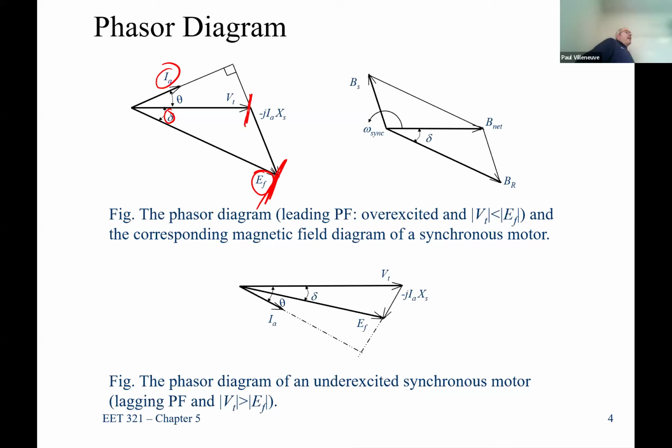So if I have a leading power factor, what does my power triangle look like? So S equals V I conjugate, right? P is always positive. Where is Q? Going down, isn't it? Because I is a positive angle. When you take the conjugate, it becomes negative. And if I take a look at that, if this is my motor, P is going in. What's the direction of Q?